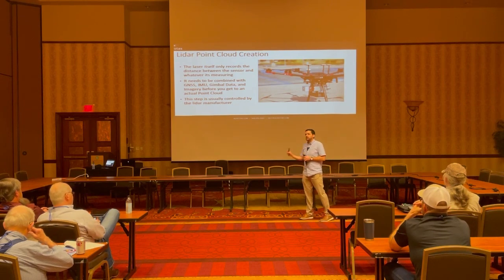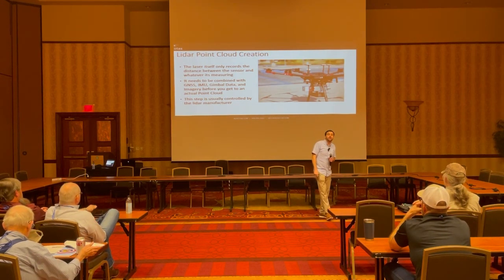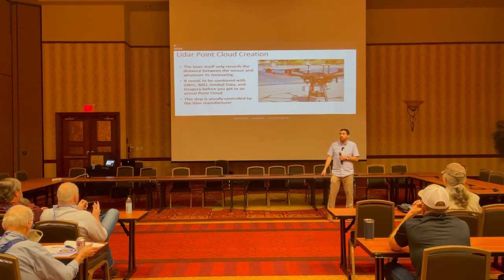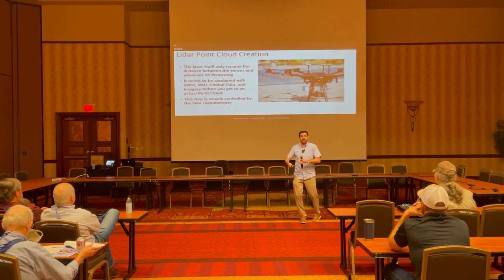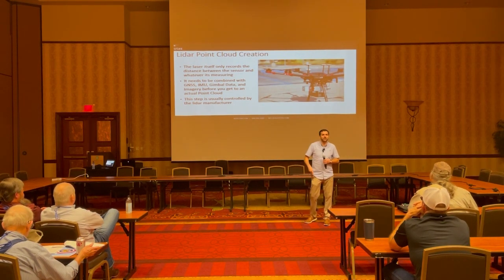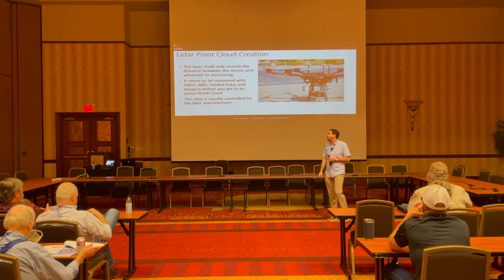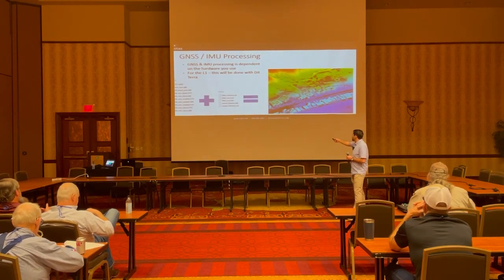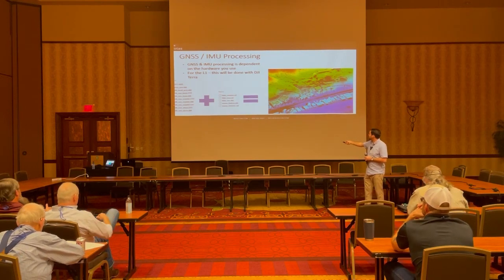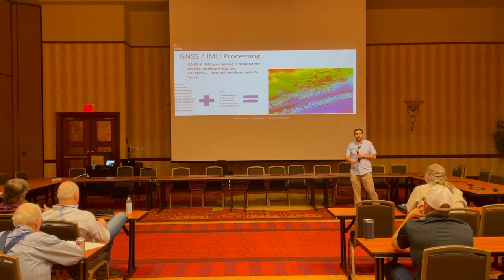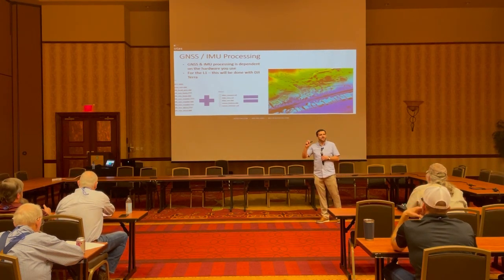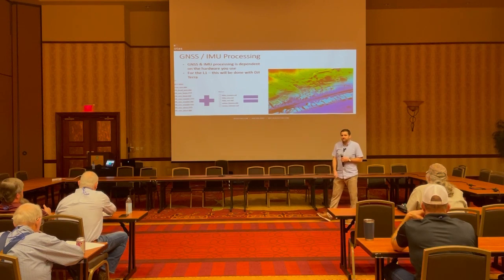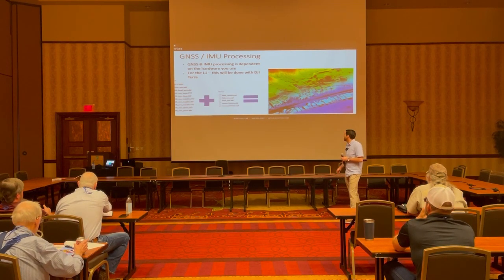This step is usually controlled by the manufacturer of the drone. They have their own proprietary software, proprietary workflow for combining all of that and getting it into a usable datum, the right coordinate system, and actually creating an LAS file, which is then going to be the input for the later on steps. So you combine all of that, and it can often look like these sorts of files. In DJI, it's done in the software called DJI Terra, which is their LiDAR pre-processing, as it's often called, to create that point cloud.